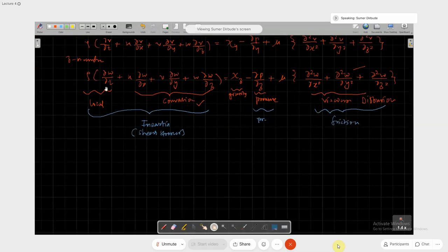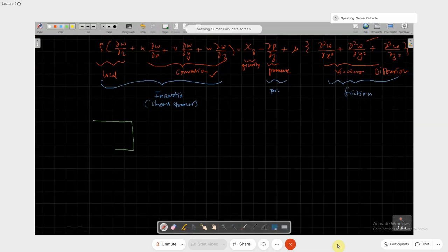So another interpretation of this local term is, say you have a piston cylinder mechanism, and you want to record the velocities at this point with respect to the motion of the piston. So what changes will you observe? Okay, since this piston is moving, the velocities of the gases are also changing. So you will see that the velocities are changing with time. This is something you can represent as del u del t, the change of u with respect to change of time. So you can say this is the local acceleration of those molecules. This is a local phenomenon, like local acceleration.